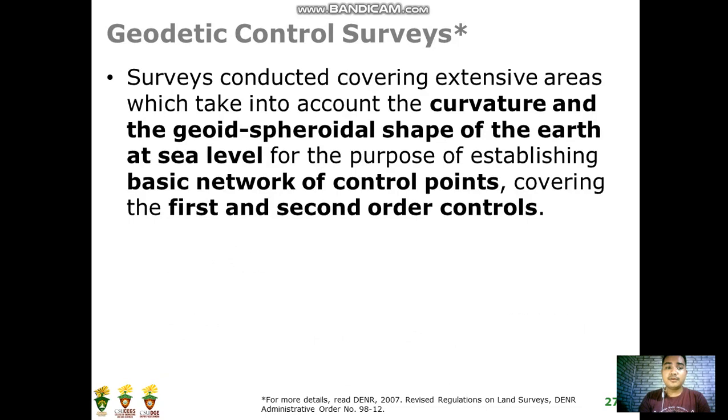And when we talk about geodetic control surveys, higher level na po siya sa project control surveys. It's because it's a survey conducted covering extensive areas which takes into account the curvature and the geoid spheroidal shape of the earth at sea level for the purpose of establishing a basic network of control points covering the first and second order of controls.